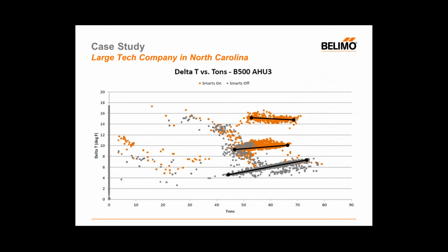And what they did was something quite experimental, and it actually follows the chart we showed you before about position control, flow control. They didn't do power control, but they did flow control with delta T limiting. So each one of the bars you see here represents a different control strategy. Across the x-axis, left to right, we have tons of cooling, and across the y-axis, going from bottom up, we have degrees of delta T, that's chilled water delta T in degrees Fahrenheit.